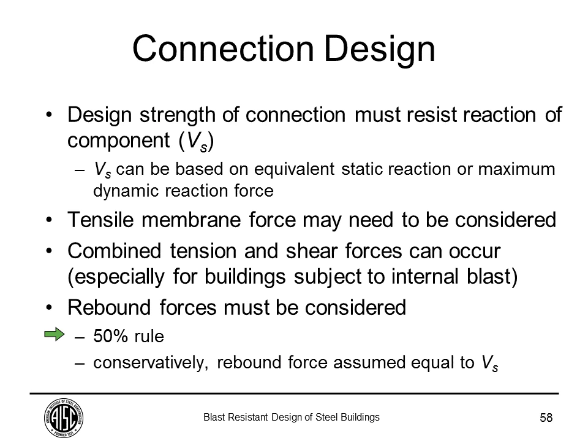If you have a component that is yielding, typically the outward reaction is going to be less, so you may use 50% of the inbound load. You could also look at the dynamic reactions from your single degree of freedom and get an idea for that reduction of the inward response versus the rebound response. But definitely, the rebound is something that you want to take into consideration. If you go back to the case of a column, where you don't have a lot of edge distance coming out of the building, you're going to have a different capacity during rebound than you have for inbound. So just keep that in mind when you design your connections.